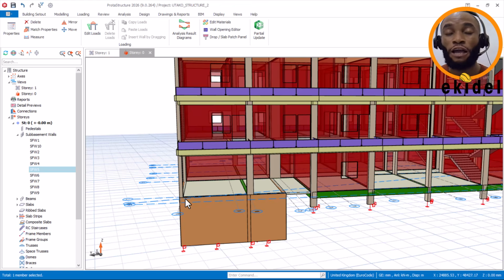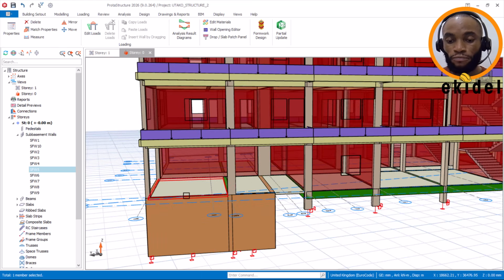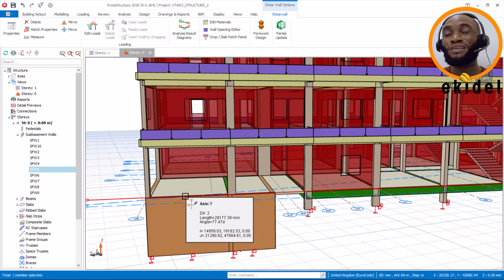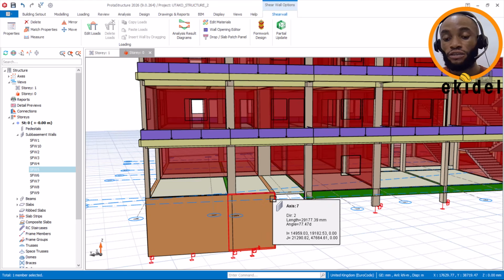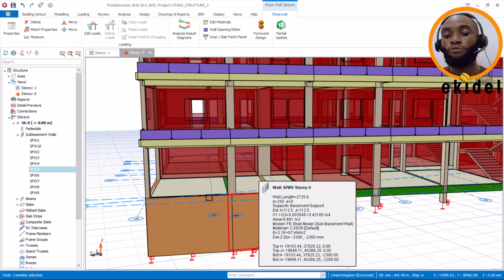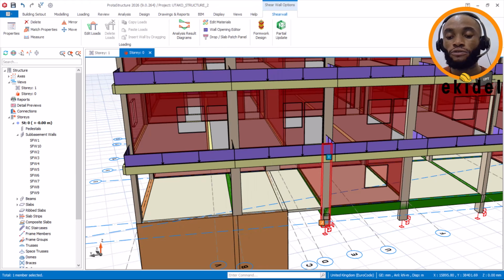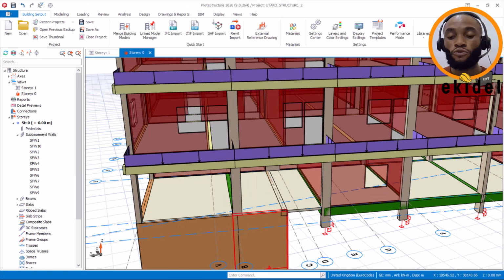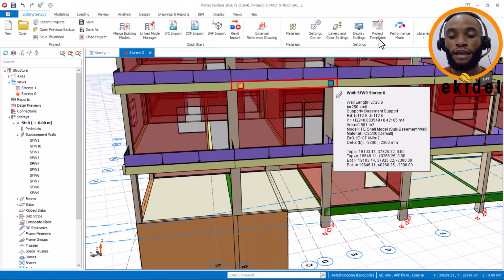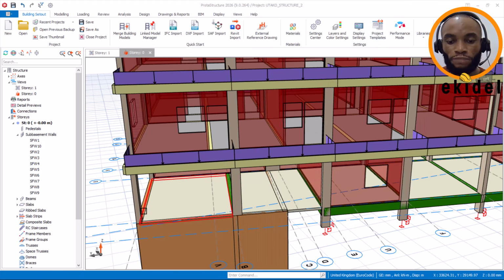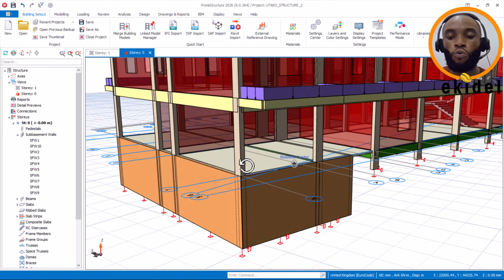Right now, on this place, there was a DPC beam which we hid previously when we started this video. So for this training, we are now going to unhide them. But now that we have a basement wall, the DPC beams will not be able to run around this place again, because those block walls are going to sit directly on the reinforced concrete basement wall.